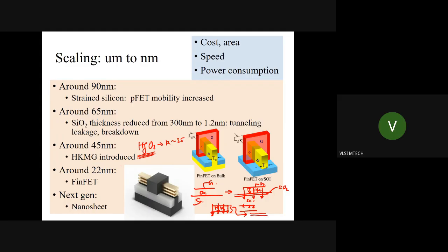So using this, what we can achieve is this thing where you have a thick physical oxide thickness. So actually, if you measure, the oxide thickness will be this thick. But as far as electrical characteristics are concerned, or as far as field penetration and all of that are concerned, to the electric field, this appears like a very thin barrier. So in effect, the electrical characteristics of the MOS device are maintained while keeping a thick oxide.